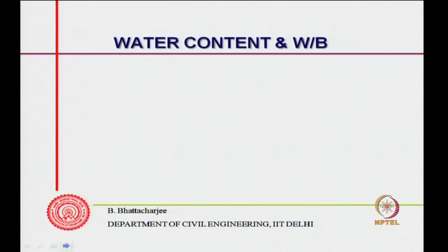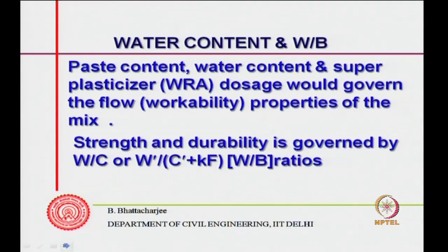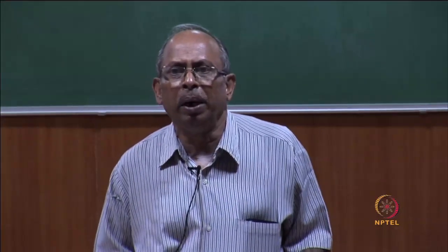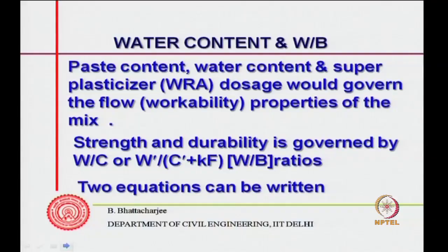Now, paste content, water content and superplasticizer dosage would govern the flow properties of the mix. That is what we have understood from our discussion right now. Strength and durability are governed by the water to cement ratio, or water to cementitious plus some Kf, which we have seen earlier, somewhat related to the water to binder ratio. This we have seen earlier, and we can write two equations based on this.